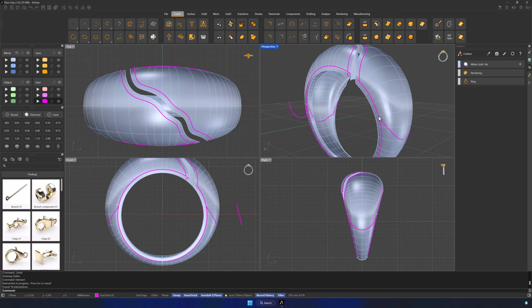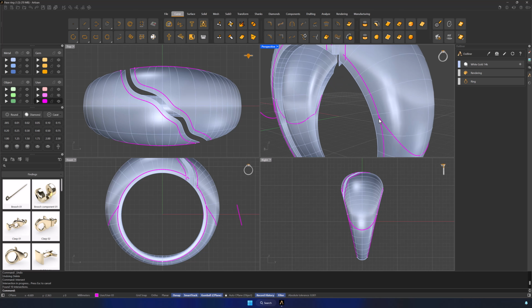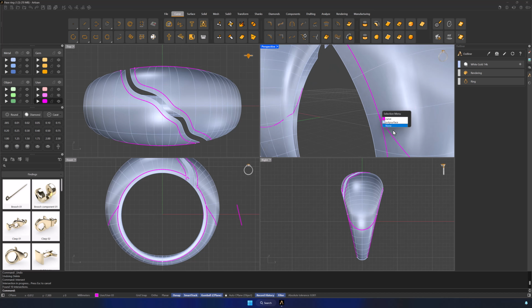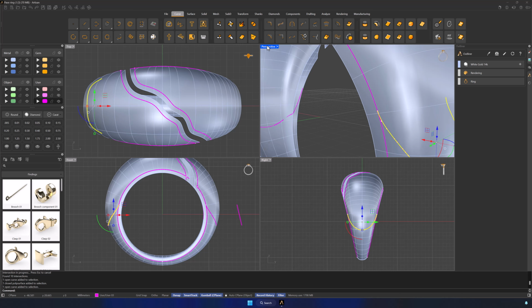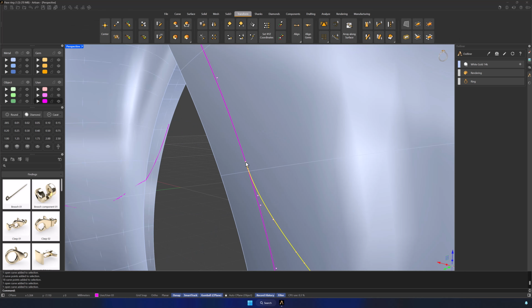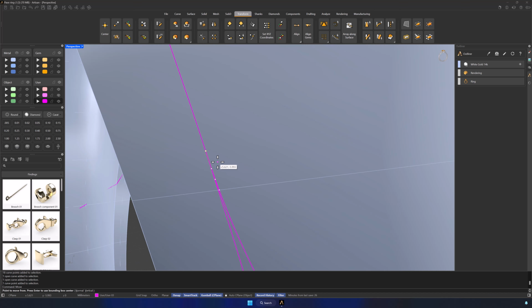However, one is missing, meaning it does not intersect. It is crucial to fix this. From the perspective view, select the inner curve. Then, select the last control point. With O-snap activated, move the point onto the curve we want to intersect with. When end knot appears, click. Check the intersection again. Now we see the intersection point has been created.